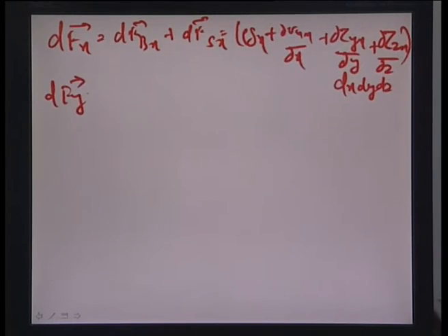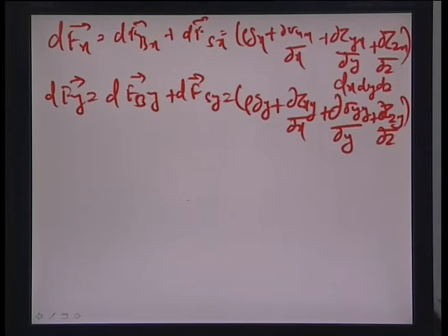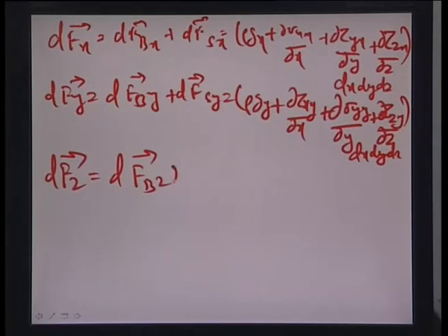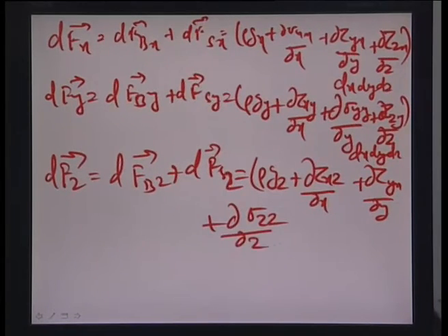Similarly dFy has a body force in the y direction plus a stress force in the y direction, which can be rho gy plus del tau xy with respect to x plus del sigma yy with respect to y plus del tau zy with respect to z, times dx dy dz, and dFz is equal to the body force in the z direction plus the stress force in the z direction, which can be rho gz plus del tau xz by del x plus del tau yz by del y plus del sigma zz, because it is not a shear force, there is a principal stress, sigma zz by del z, times dx dy dz.